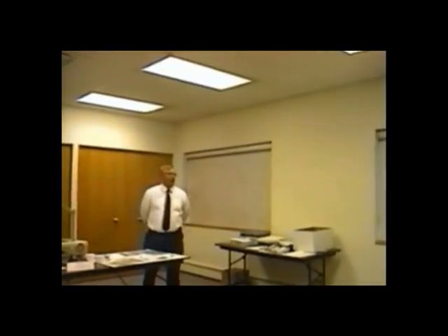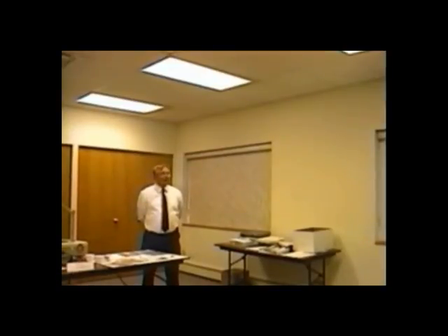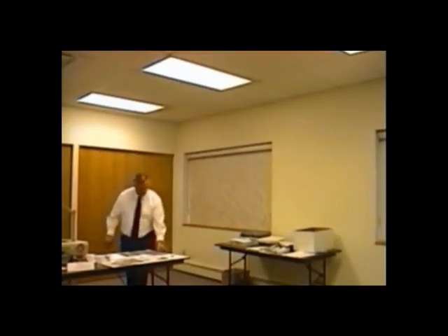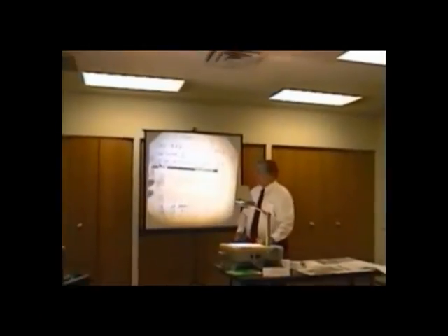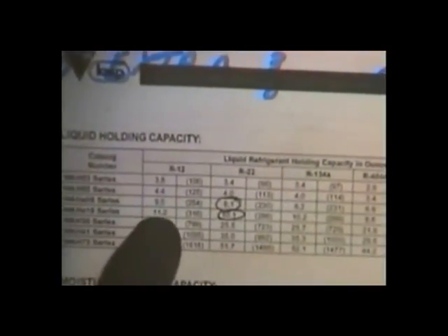Let's talk. Because we're a good contractor, we're going to spend that $7 or $8 extra and put in a liquid line dryer before the metering device inside the house in the shade pointed down. And because it's a liquid line dryer, it holds refrigerant. We have to add refrigerant for that. So would you now please turn over to page 8, and are you going to love this? I'm going to keep my notes up here, but I have the other copy. This is a tech data sheet that I just got yesterday. It's an updated sheet, and it shows the 2 size dryers that we use, ladies and gentlemen.